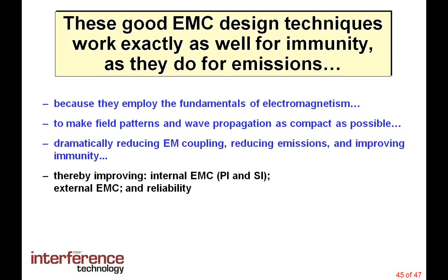So we improve our internal EMC, our power integrity and signal integrity, so we don't have to have so many design iterations to get the product working to spec and get the software reliable and stable. It improves external EMC, and it also improves reliability. This is the thing people often overlook. Products designed to have better EMC work more reliably in real life and reduce the warranty costs.